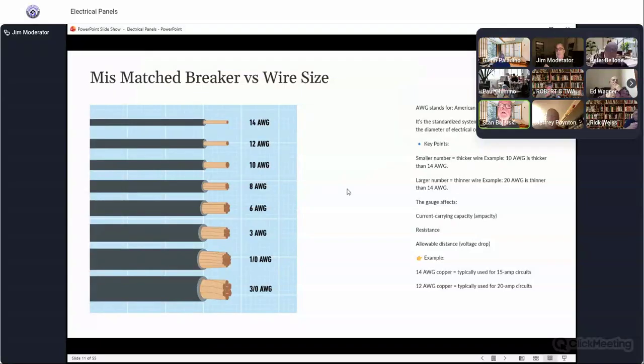Sometimes, with the insulation, you're looking at two wires that look very similar. You have to look at the wire coming out if you can. Sometimes it's stuffed in the breaker so far that you can't see the copper, and sometimes it's misleading just looking at the insulation, because they could be very close. So if you have any questions, write it up and tell them to have an electrician look at it. That's your out if you're unclear, and you really need to be very careful with the electrical system.